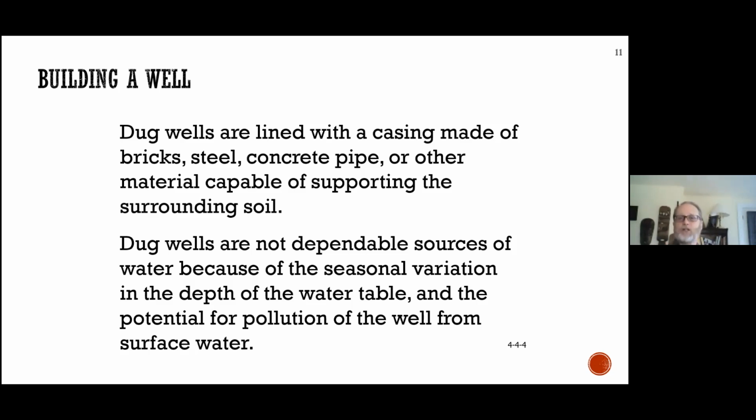A different agency actually took over running that utility because the operators of the system, actually, none of them had ever written a certification exam. They were grandfathered, so they didn't really understand how a water system should be run. They didn't make the people sick. The wastewater contamination, fecal coliforms in the water made people sick. But their lack of understanding of how those wells really operated was a huge contributing factor to those people getting sick and dying. So no matter how the well is constructed, that's really so critical.